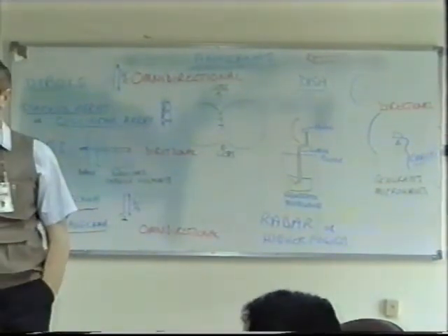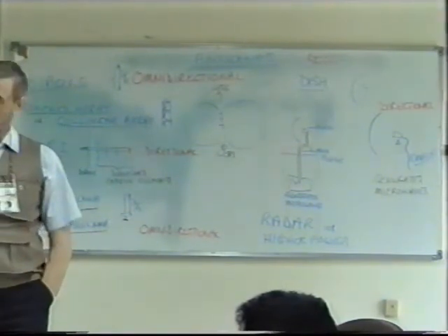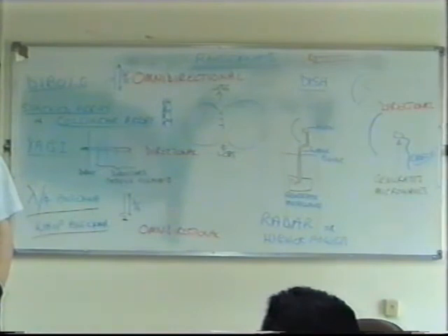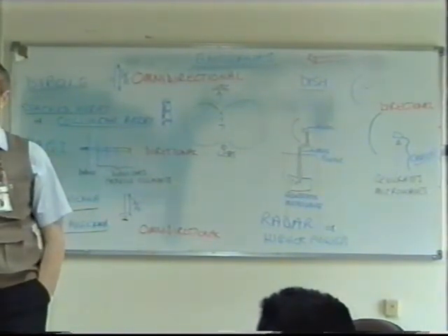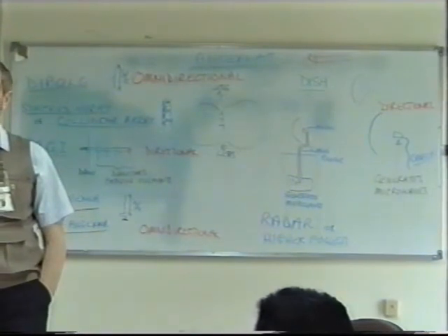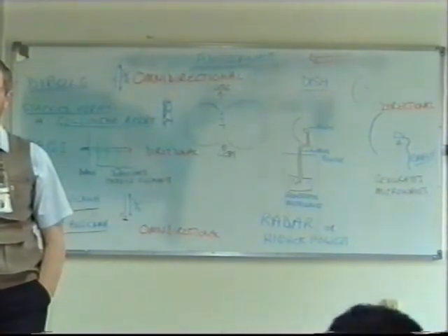That one looks to me as though it's like that, isn't it? Yes. That's horizontal, so you should have your receiving antenna the same. And if it's vertical, it would be like that. Because the electric field is what induces the voltage, so that we receive the signal.